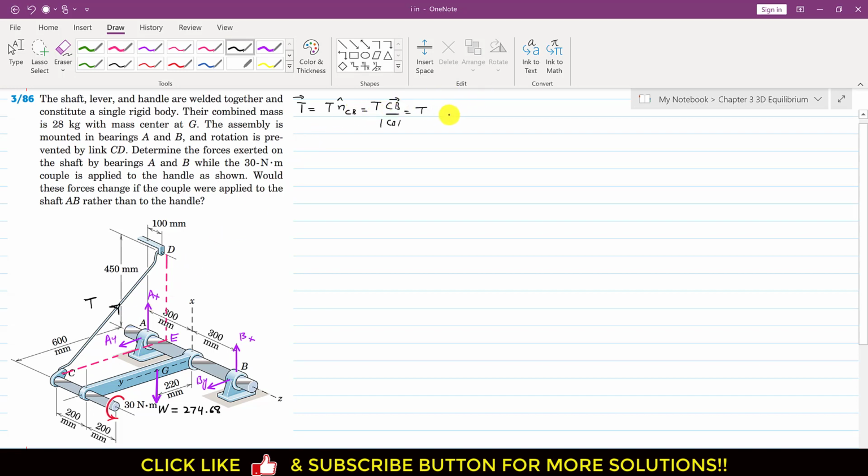So now this is T and we can find this CB vector, right? So how to find this CB vector? So we will travel 600 mm distance in the Y direction and then we will travel 450 mm distance in the X direction, right? So in the X direction we will travel 450 mm in the positive X direction, so 450 divided by 1000, so that is 0.45 meters, 0.45 meters in the I direction, and 600 divided by 1000 is 0.6 meters in the negative Y direction, right? So we will write minus